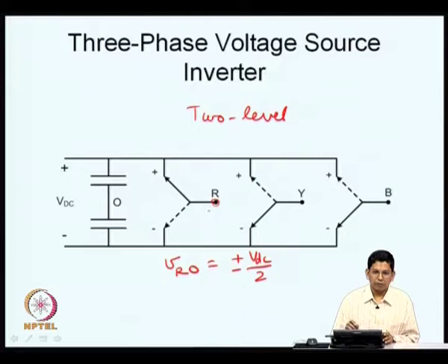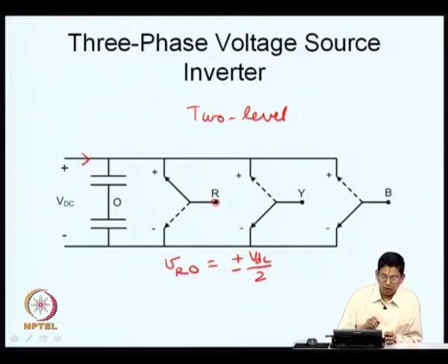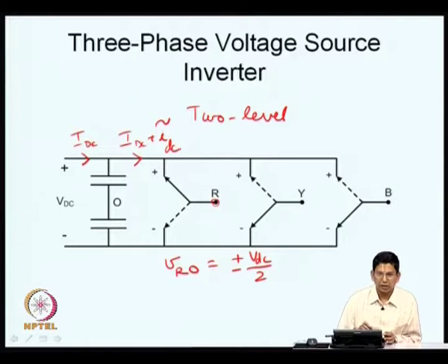And as was also remarked earlier, this is really a bidirectional power converter. Power can actually flow in both directions. It is not necessary that it needs to flow from the DC side to the AC side. You have a DC supply here, let us say current can be flowing like this, and this can be DC plus ripple flowing like this. Let me call this IDC, and this IDC plus I tilde, a certain ripple current. I will also call it I tilde DC just to say that it is on the DC side.